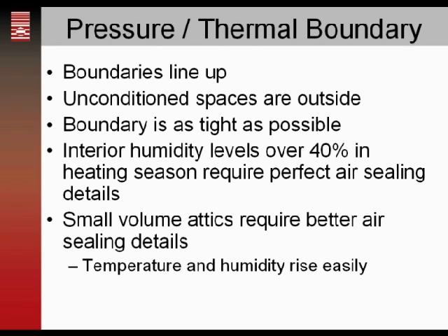Otherwise, you're going to have these attic condensation issues and durability issues. Small volume attics require better air sealing details because the temperature and relative humidity levels can rise easily because of that small volume.